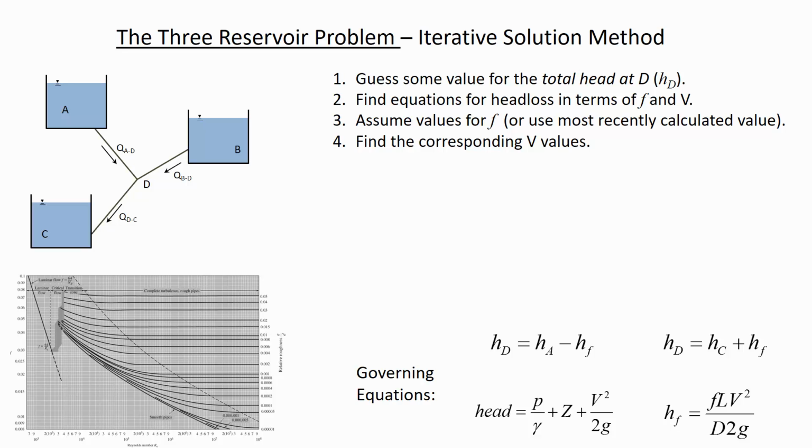Only that you would have to calculate your head differently. If it was an enclosed tank and you were given the pressure in the head space is some pressure, 250 kPa, for instance, then you'd calculate your head at A equal to its elevation plus its pressure head if it was enclosed. So we can handle that. We just need to know what's the pressure in the head space if it's not open. In other words, the both tanks have to be the same height. That's right. Yeah, the tanks can have any diameter and any height, and we'll be able to solve this problem.